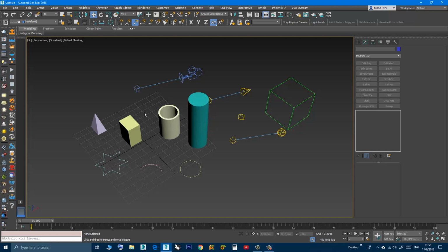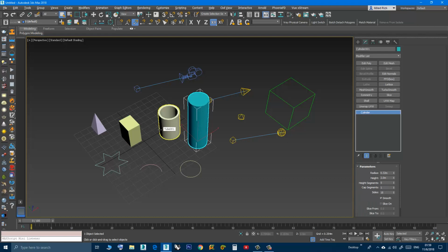So it's more safe to click on select object. It's just so you can select freely without this risk of transforming your objects by mistake. The shortcut for this is Q. We already said that move, rotate, and scale are W, E, and R. The select only is Q.